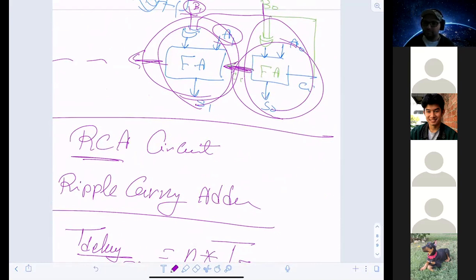So what is the T delay? Is it just the delay, like, how much time this will take? Okay, so you have to do the first one before you go to the next one. Exactly. So you know how many repeated blocks there will be, times the delay of one of them will give me how much time the whole entire circuit will take to give me an output.